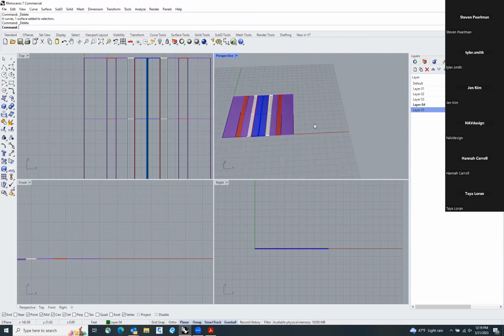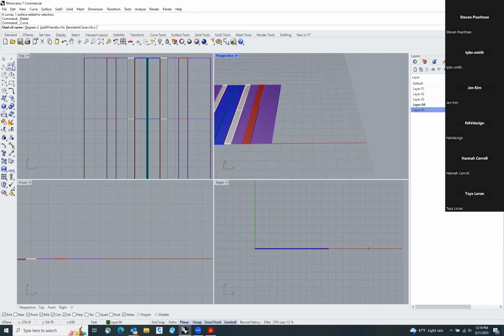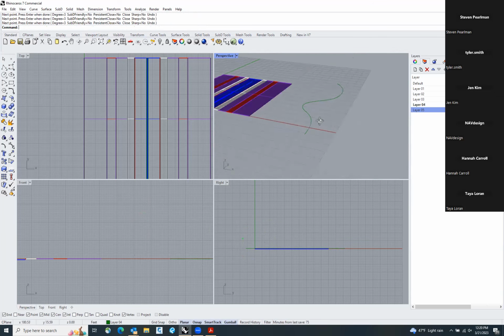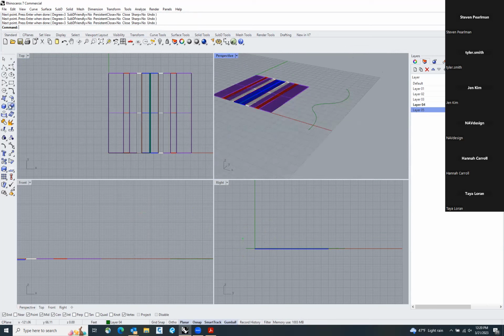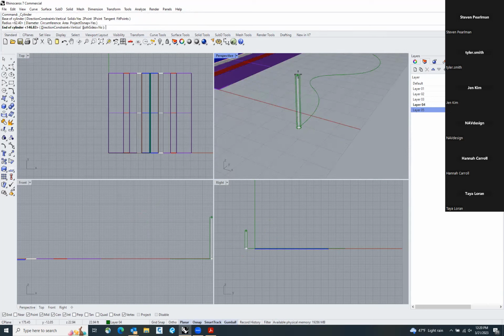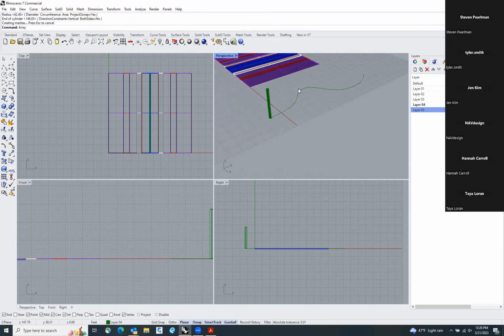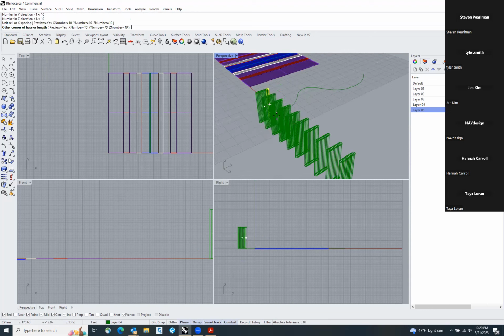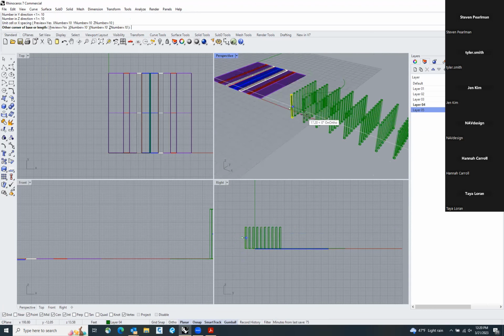I had several other, I'll do a couple more really quick, but here's some that I use a ton. So I'm just going to draw a line here in the perspective view. And I'm just going to make a sphere here in the 2D view. Array is very similar to CAD. So if you type in array, select objects, that will allow you to just array in the X, Y, and Z dimension. And then you can do the spacing and you can see kind of what that looks like.